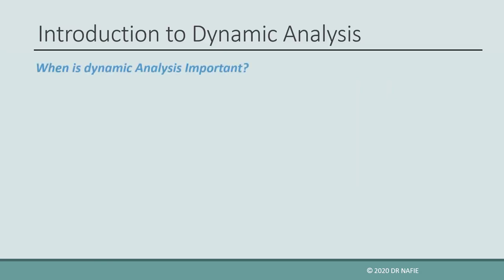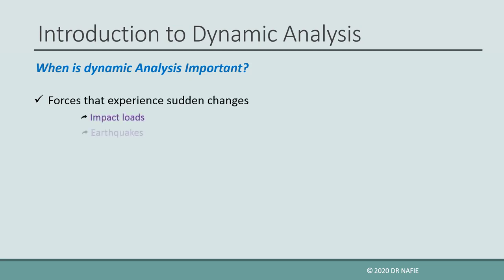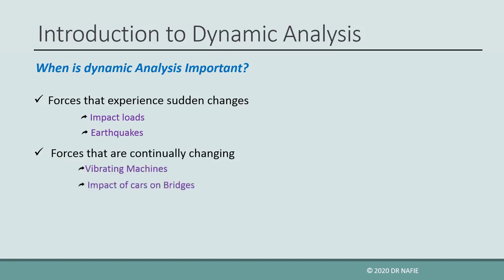So, when is it important to consider performing a dynamic analysis? From the preceding example, it is clear that the dynamic effect is a temporary effect that is caused by sudden variation in load. Dynamic effects become important in cases where there is a sudden change in the loads, such as impact loads and earthquakes, or when the load is continuously changing, such as structures supporting vibrating machines and due to the effect of moving cars on bridges.